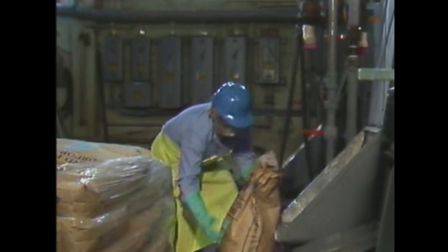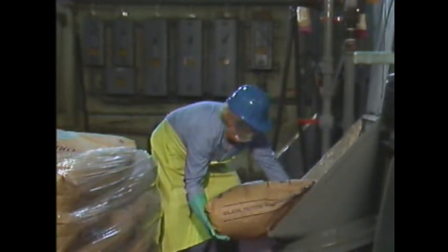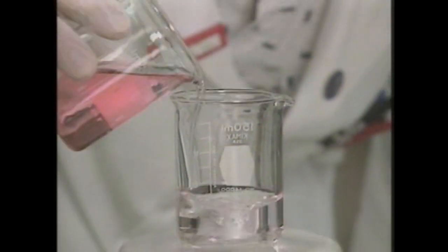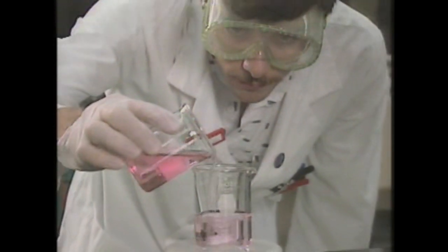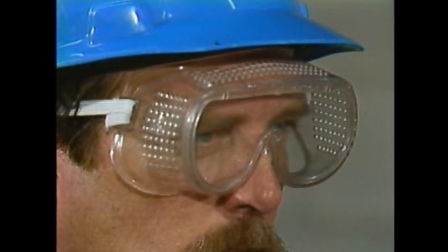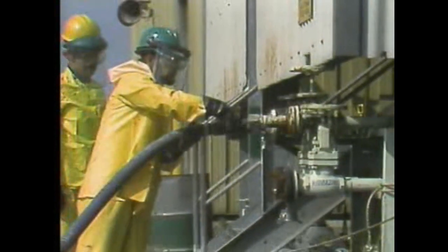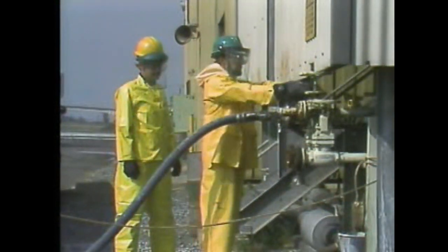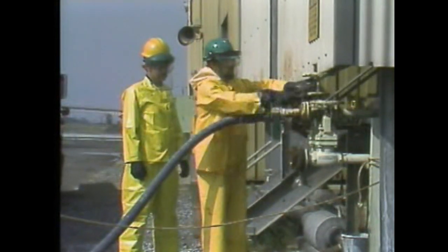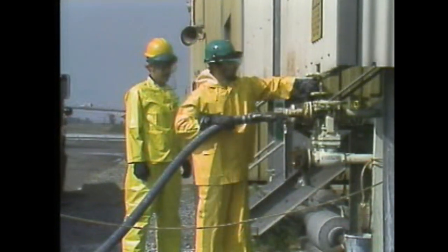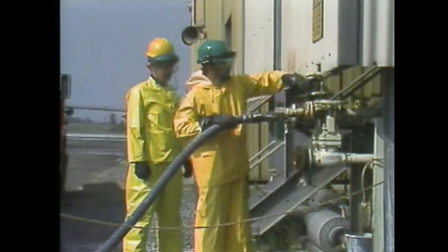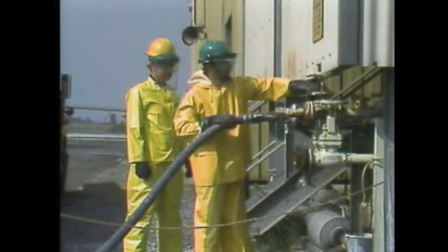For instance, some types of goggles are better at protecting against dusts and fumes, while other types of goggles are better suited to protect you from splashing liquids or flying particles. So make sure you choose the right type of goggles for the hazard. And the goggles must be in good condition and fitted properly. Most goggles can be adjusted so that they fit snugly against the face. Some jobs require that a face shield be worn along with goggles to protect all of the face. A face shield is designed primarily to protect your face from flying particles or splashing liquids, but it is also considered a secondary means of protection for your eyes.